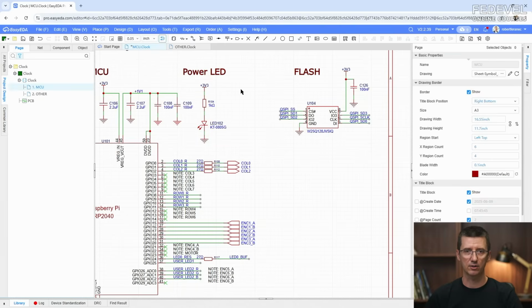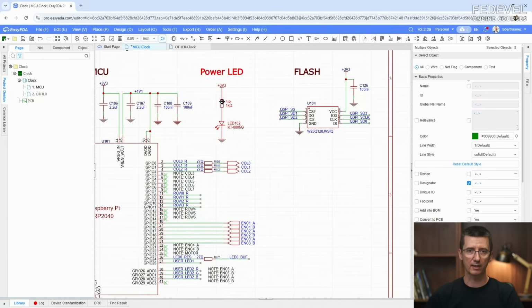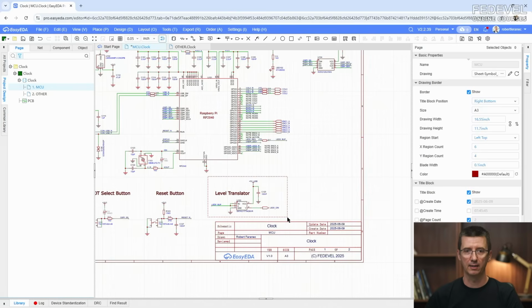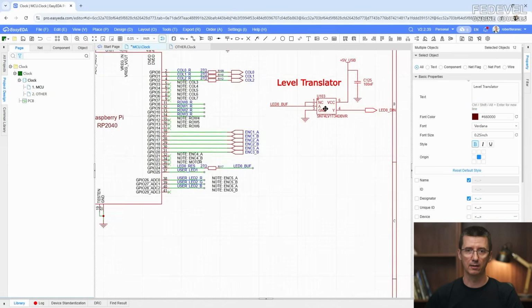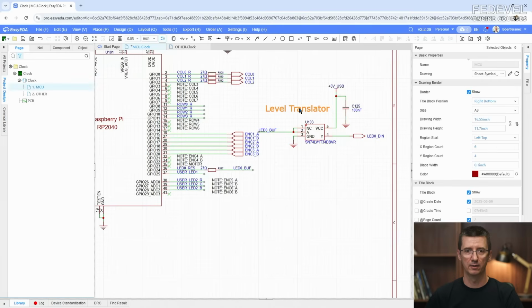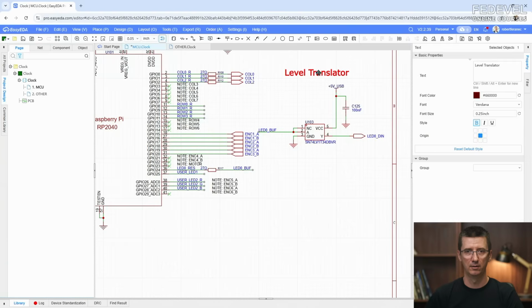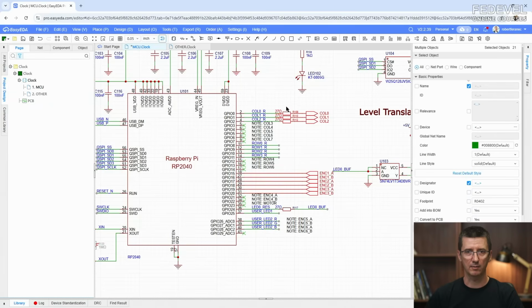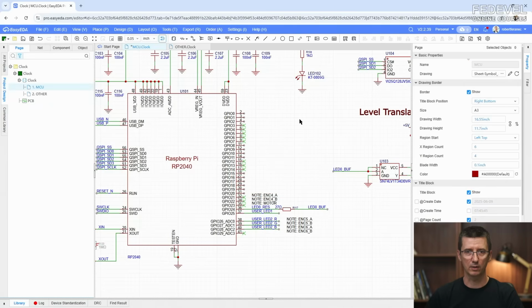Notice these selections. If you do it from left top or bottom right, there is difference. From top left, only what is inside of this selection rectangle will be selected. From bottom right, everything what is inside and what is touching the selection rectangle will be selected. I'm making everything nicer. Okay. We can delete many of these. So you can use delete on your keyboard.